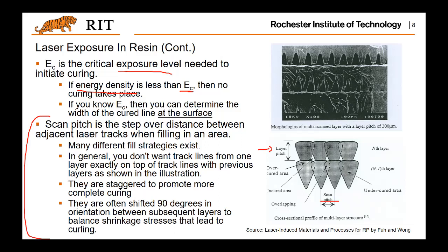So definitely you want to minimize these voids in between each of the traces and also in between the different layers. So you definitely want appropriate pitches, both between layers and between traces. This is critical to tune in such a process.